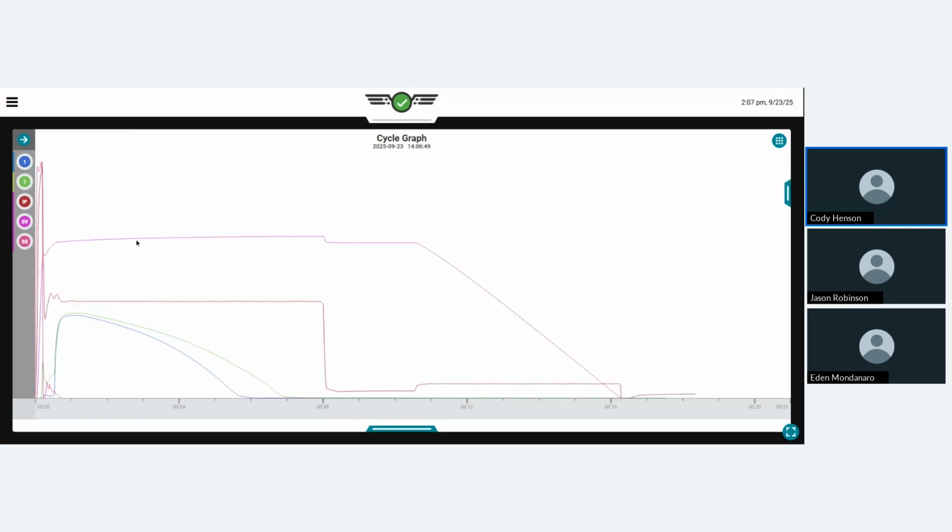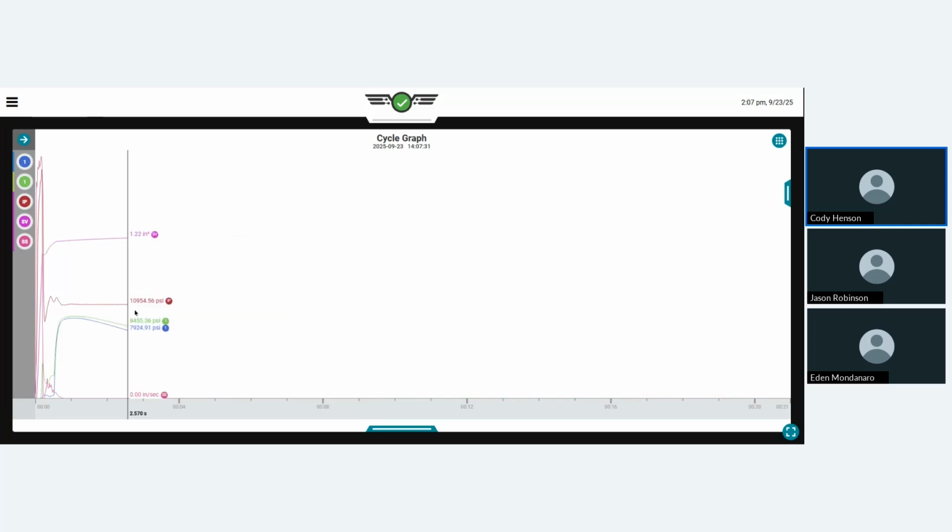When you navigate, you may touch the screen to kind of place this cursor. I'm going to be clicking around and moving. But when you place the cursor in a location, you can start to pull values that we care about from the CoPilot. So you may be seeing some values for the stroke, some values in plastic specific pressure for the hydraulic.